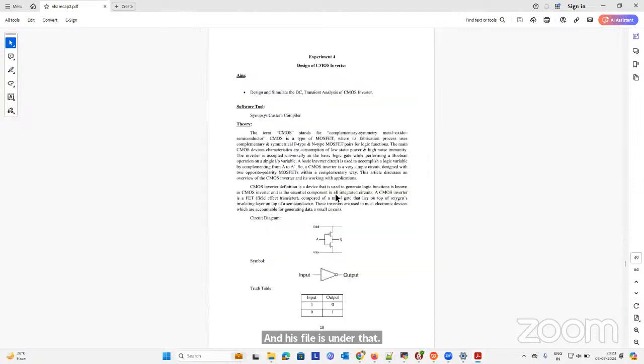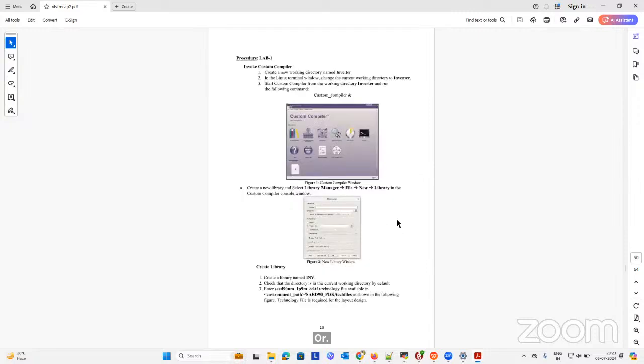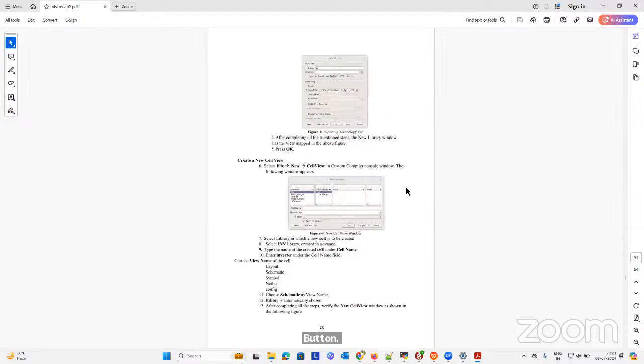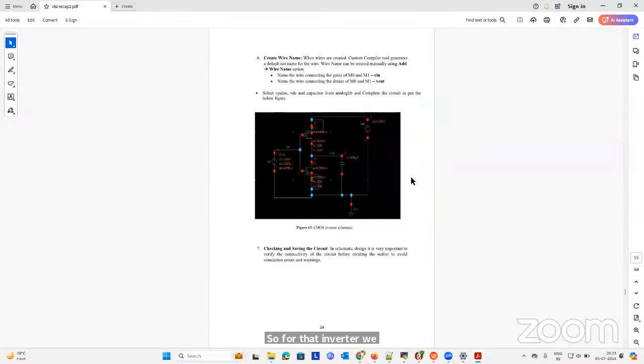Next is the design of a CMOS inverter. So this is covered as a part of analog simulation in Cadence Virtuoso. So what we have done is, we have done a Cadence circuit design of an inverter. For that inverter, we have written an analog mixed signal test bench using ADE Assembler. So for that, they are having a functionality.